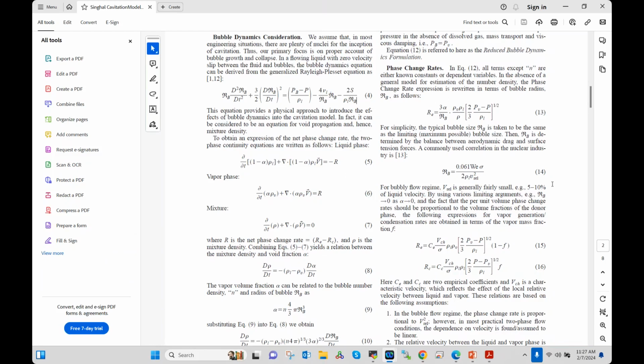Also in some cases where the dynamics are more complex, where it is important to understand some time constants for the dissolution of gas into liquid or getting into free or dissolved gas, we know that we have to use the more complex models. But in general, for centrifugal pumps, I would say the constant gas mass fraction model does a very good job.